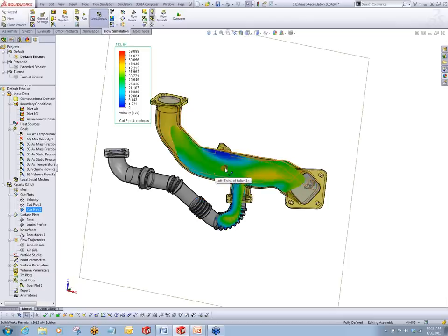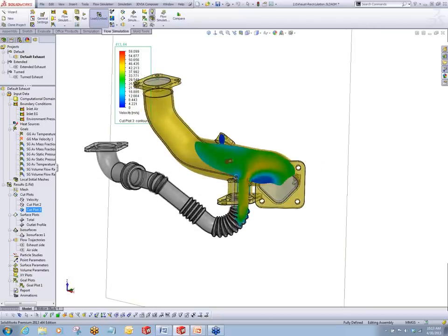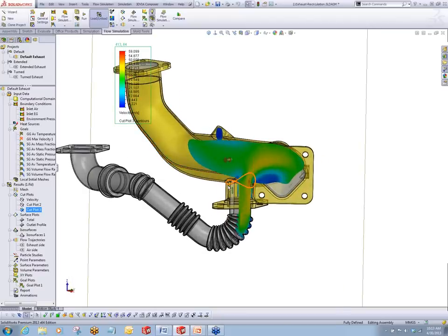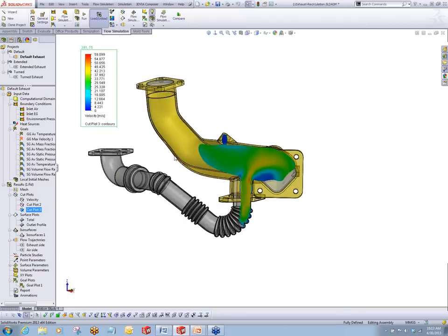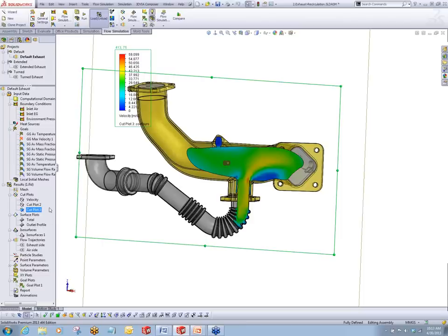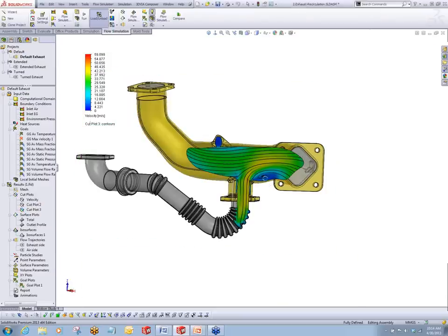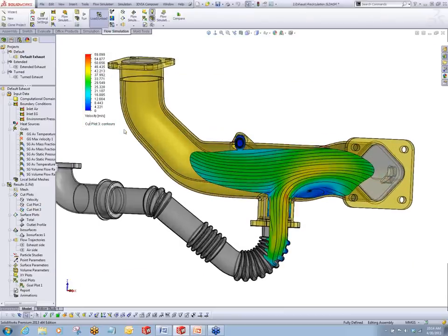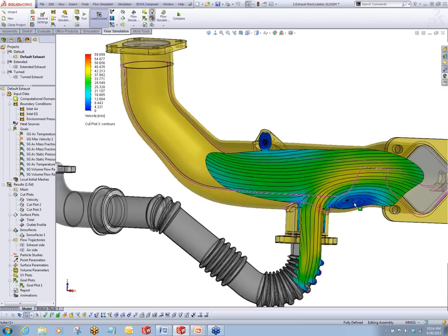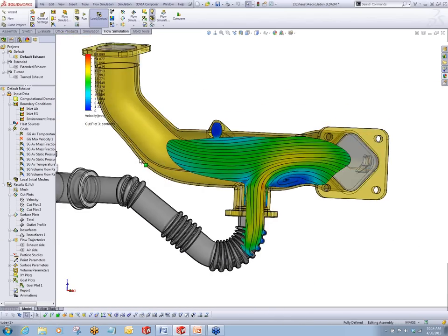We can move that to show the various positions, and you see we have velocities that are getting kind of stagnated where this inlet comes in. Moving this over here, we can also overlay the streamlines on that, as I showed with the other one. Let me go ahead and do that for this one. Turn on the streamline plot. There you see, as we get into these areas of recirculation zones, we see that very nicely visualized with the streamlines overlaid on our velocity plot.